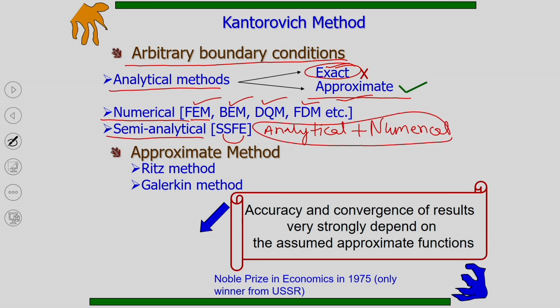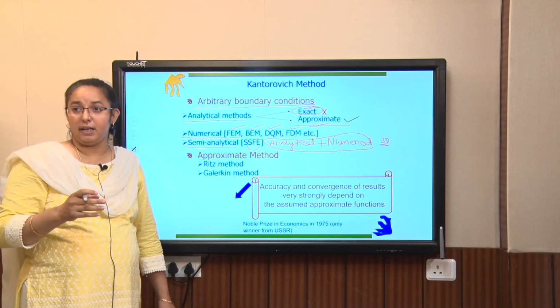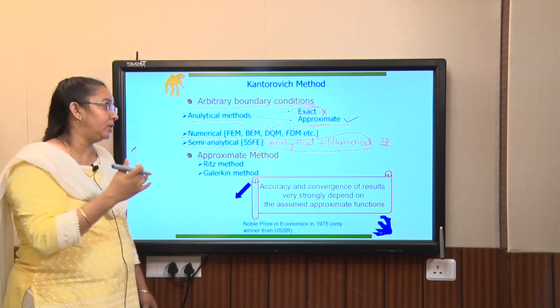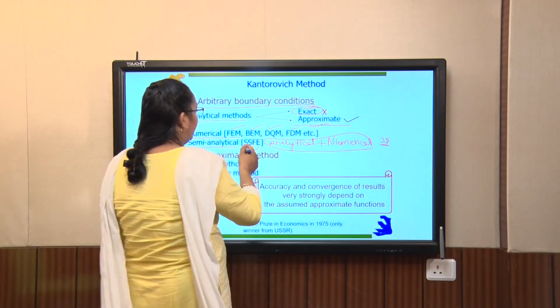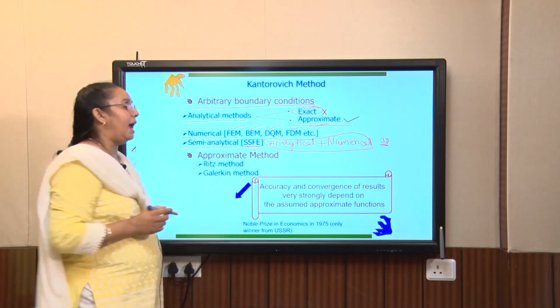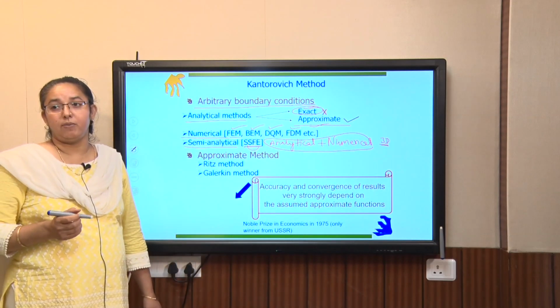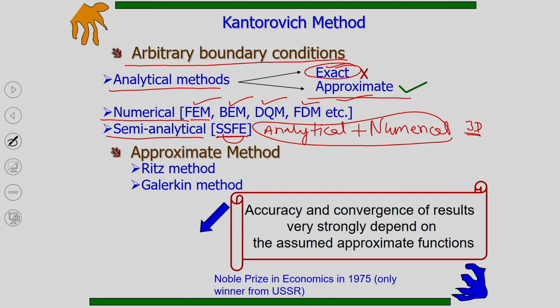Basically when we are talking about 3-dimensional solutions, 3D solutions, the partial differential equation will be in x, y and z. So for those cases we generally solve along the z direction analytically and x and y using the finite element. That technique is known as SSFE, state space finite element, or sometimes SSDQM. Recently some of the researchers are using these techniques.